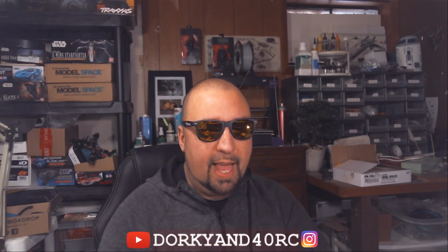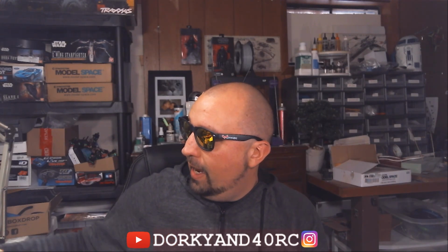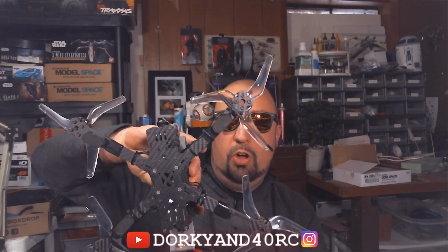And diversity or not, I think the biggest takeaway from this video is get your antennas out away from the quad. Horizontally on the arms as far as you can, or vertically all the way up where nothing is blocking any of the antenna. Now, some people might disagree, many people will agree, but I feel even that extra 2 inches on this rear antenna right here, or 1.5 inches, would make a huge difference in performance, how this thing is working. We saw it on the Flight 1 video that I'll put a link up here for. You can see how much of a difference it made. I'm tempted to even just unplug one of the antennas from this and fly it and see how good it does with just the antenna all the way out on the end of a 7-inch arm away from anything.